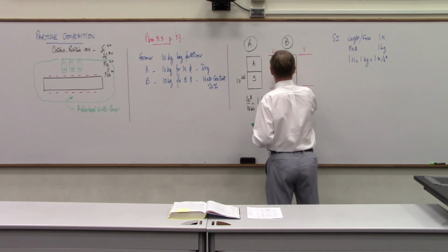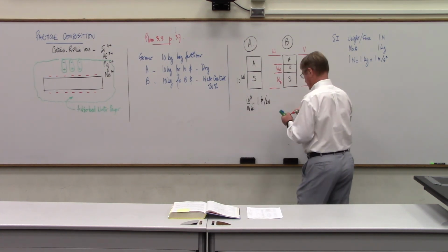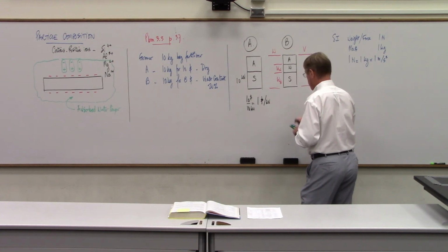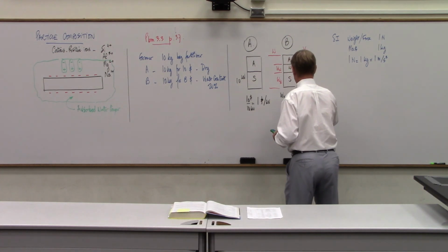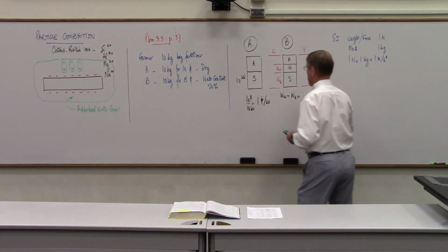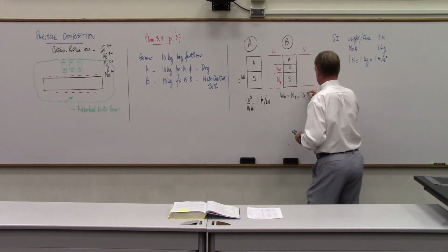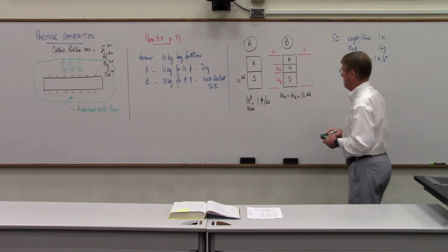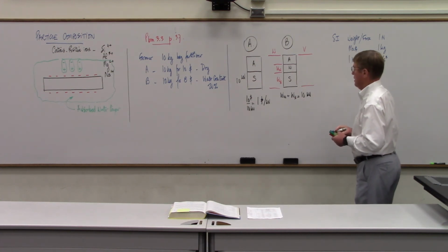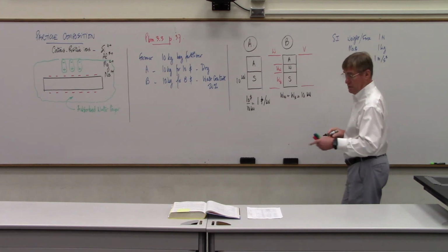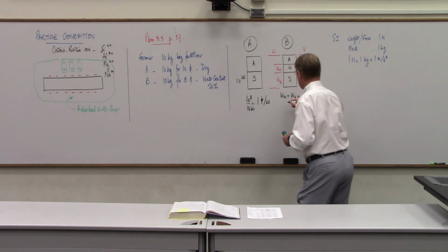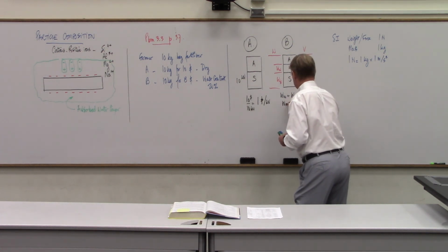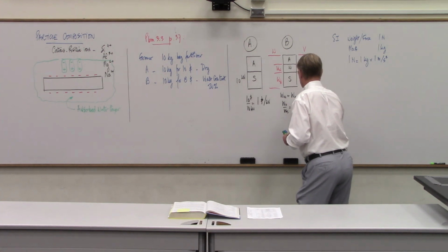So now we know that the weight of water plus the weight of solids equals 10 kilonewton. What else do I know? Well, the bag says 20% water content, so I know that the weight of water over the weight of solids is equal to 0.2.